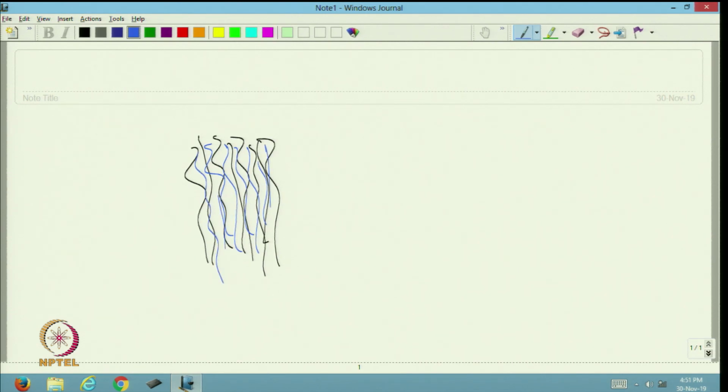We assume that in hybrid yarn the matrix component will melt and it will be in between the space of the reinforcing fibers, but we cannot guarantee that all the filaments will be coated or covered with the matrix component evenly.